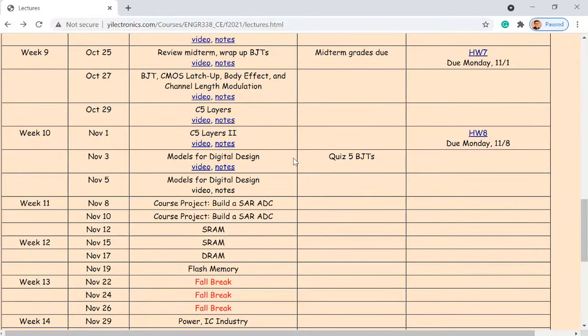So none of the components in the SAR ADC design of the course project will be an ideal block, or some of the ideal boxes you have used in the first level of this class. So this design will be fabricatable. I mean, all these are transistors. So we have done that. I'm going to give you examples of it, and we'll add a little bit of detail regarding how to calculate DNLs and INLs.